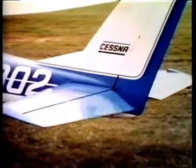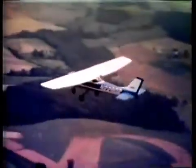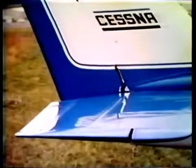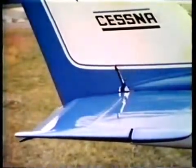Elevators are hinged surfaces connected to the horizontal stabilizer. They work in the same way as the rudder. Moving the elevators varies the angle of attack of the airplane. This small control surface is called a trim tab, and it is an aerodynamic device used to ease the pressure on pilot controls by creating enough lift in the segment to hold the control surface in position aerodynamically.